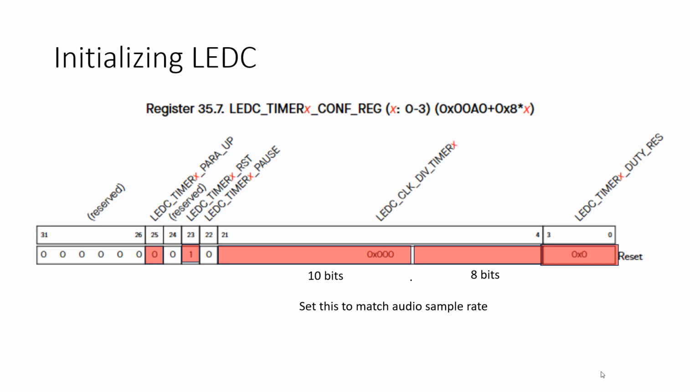The problem with us, though, is that we have very limited memory on this thing, right? So we don't necessarily want to use 48 or 44 kilohertz. We want to use a lower sample rate, just because we want to be able to fit. The higher the sample rate, the larger the file size, especially since we're recording this as raw audio. It's not compressed like an MP3, right? You guys with me? We're doing lossless audio.